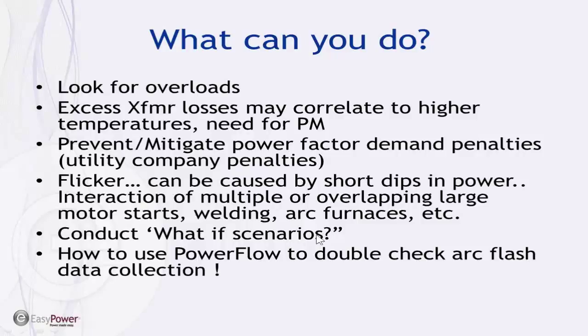Likewise, you can also look at what-if scenarios. If you need to understand what your system is going to do if you make changes to it, load flow is the first place to go. I think that's probably the most obvious day-to-day use of the tools from that point of view. And then you can also use load flow or power flow to determine whether your data collection during an arc flash study is accurate or on track.